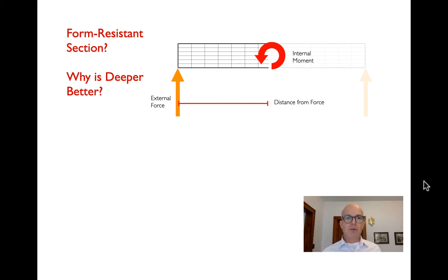And you might remember that we said that, okay, well, if we do our free body exercise and we slice a beam and try to sum up all of the forces acting on this free body and think about what we need to resist it, in a simply supported beam, we have an external force. This is before we get to any applied load. And as we track our way along the beam, we have an external force. In this case, it was the reaction that's trying to twist the beam in a clockwise direction.